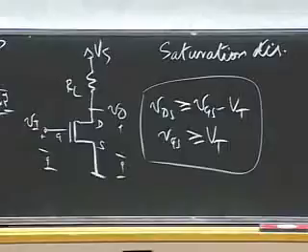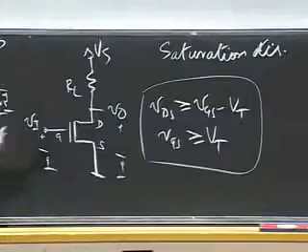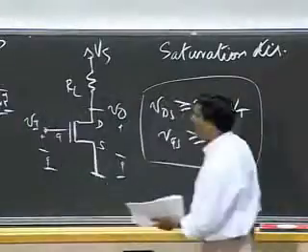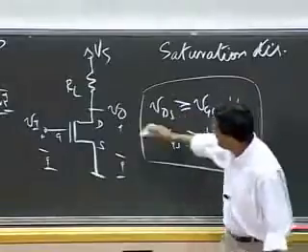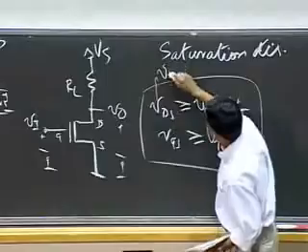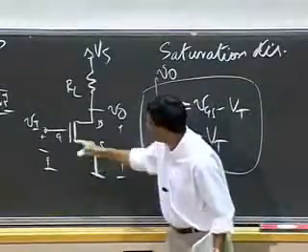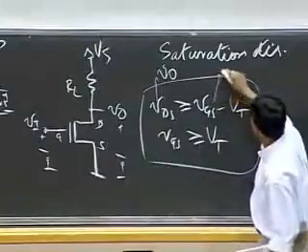Okay, and homework problems and so on will state that: assume that the MOSFETs are in saturation. What that means is that you can begin to model them as a current source and simply analyze the behavior accordingly. One minor note: VDS for the MOSFET is the same as V0, and VGS for the MOSFET is the same as VI.